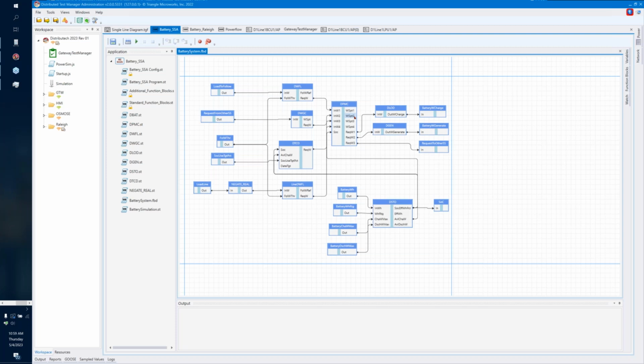But in this case, that is what we've done. So in some ways, it looks a little bit similar to what we saw over in Test3 Pro with our signal flow diagram, with signals flowing from one logical node to another. But at this specification stage, we've not yet associated these logical nodes with IEDs. So these may end up being a GOOSE message should these two logical nodes one day exist on different devices, but it's also possible that this will all be logic internal to a single device.